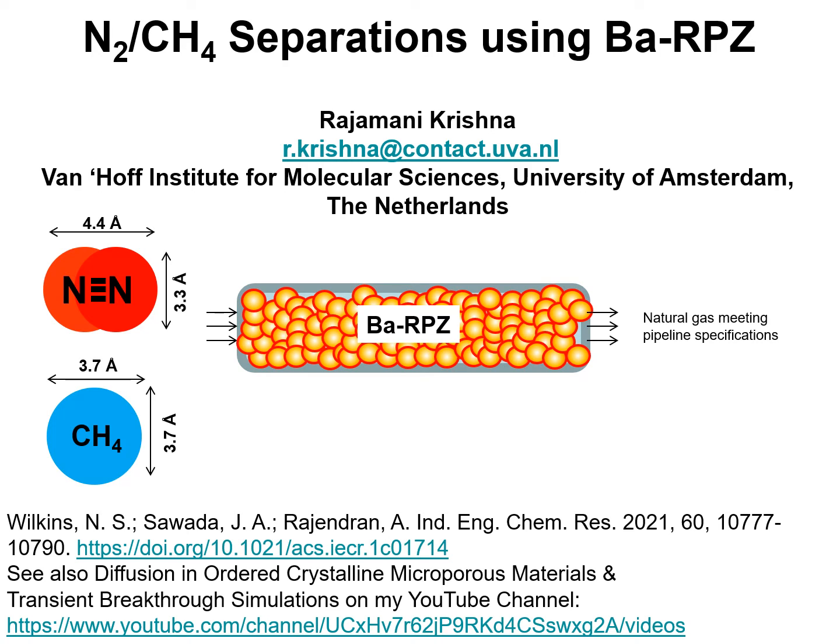Many natural gas reserves contain nitrogen in concentrations ranging to about 20%. To meet pipeline specifications, the nitrogen level must be reduced to below about 4%. A large majority of nitrogen removal facilities use cryogenic distillation, but such units are economical only for large capacity wells. For smaller reserves, pressure swing adsorption technology has economic benefits, especially because the feed mixtures are available at high pressures.